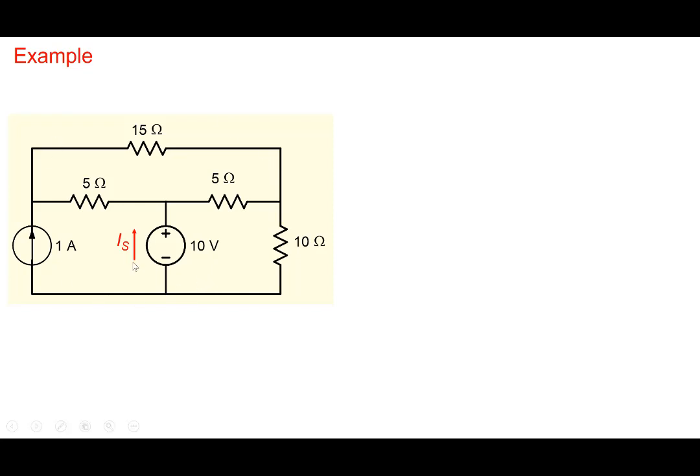So we have a circuit like this. First step, remember, we identify all the nodes. So 1, 2, 3, 4, here 4 nodes, and we number them, and we choose one as a reference node. So again, we choose this as a reference node. This becomes ground, and the value of the other node then becomes 10 volt here. So that makes it easy. And we number them 1, 2, 3. There's no need to number the ground node here. You could take it as 0, let's say.